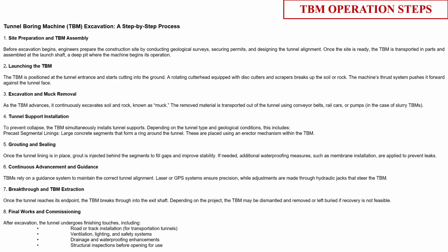If it is a very smooth type of ground, or a very favorable ground for the TBM, where you don't have groundwater seepage, or the ground stiffness is very high, then you can excavate the ground by the TBM, and the advance rate can be 10 to 15 rings, sometimes 12 rings per day. Each ring will be 1.2 meter to 1.4 meter wide. So approximately in each shift, it can be 15 to 20 meter. So in both shifts, it can be 40 meter to 50 meter.